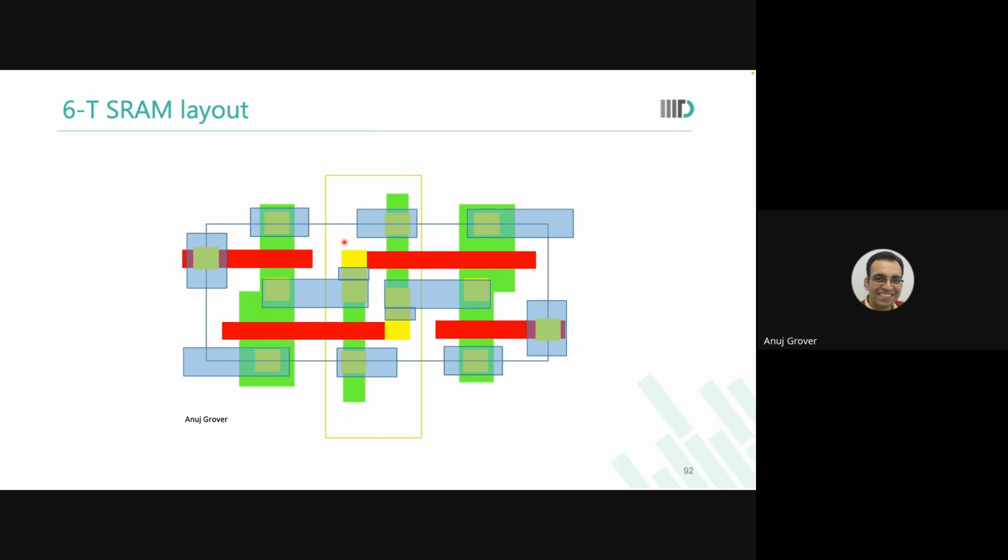And here again, do you notice that I'm not really covering all the contacts fully. Again, this is allowed only inside the memory cell, only because the structure is very standard, is not being changed, and only because I want to reduce area. Area is diamond. So since I am doing all such violations until metal 1 layer, whichever company you go to, they will not allow you to touch anything up till metal 1 inside your memory cells.